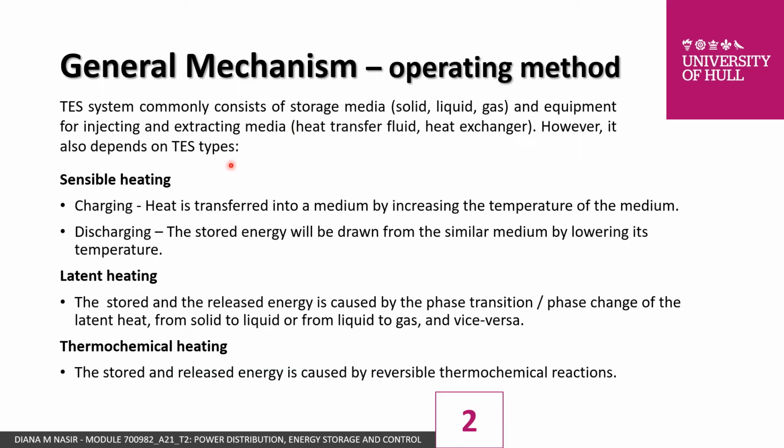In general, TESS requires storage media such as the solid, liquid, and gas, and the equipment which injects and extracts the media, such as heat transfer fluid or heat exchanger. However, it depends on which type of TESS techniques we apply for. There are three methods to charge and discharge the energy using the thermal operation. Number one is the sensible heating, number two, latent heating, and next one will be thermochemical heating.